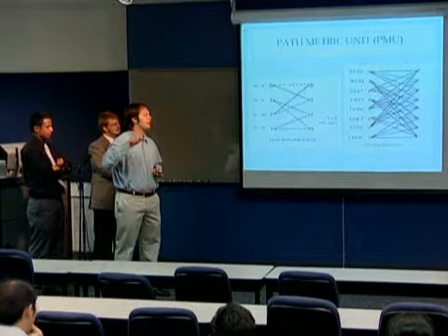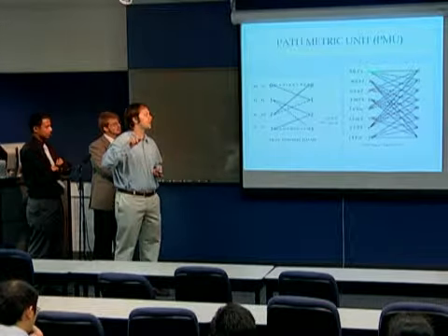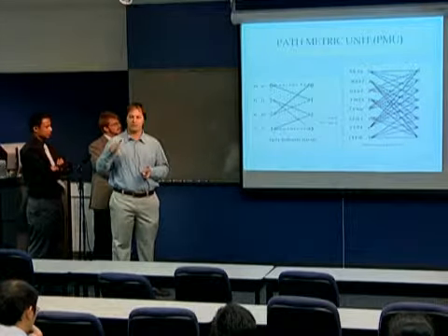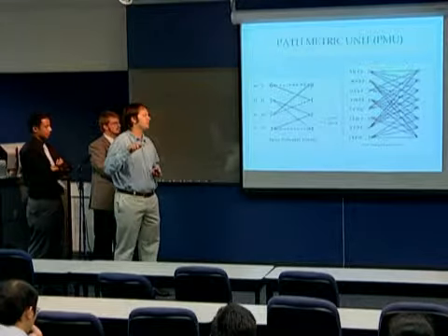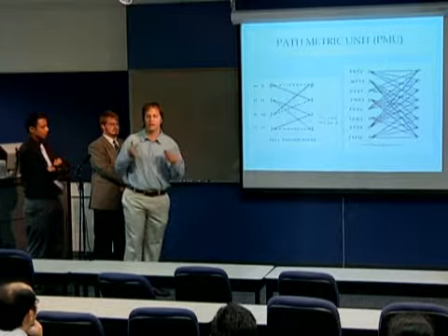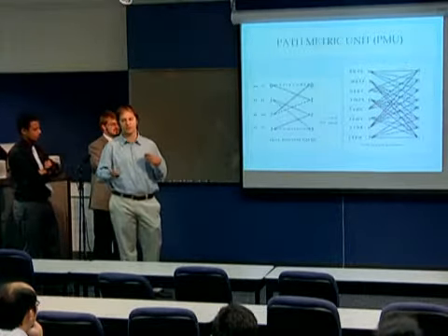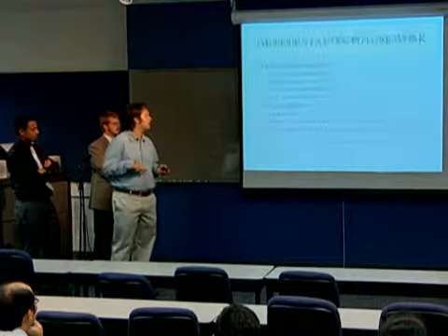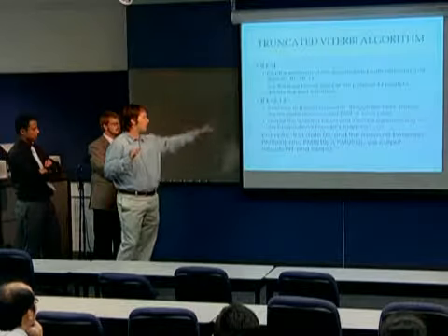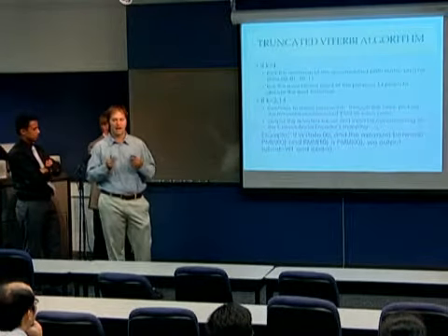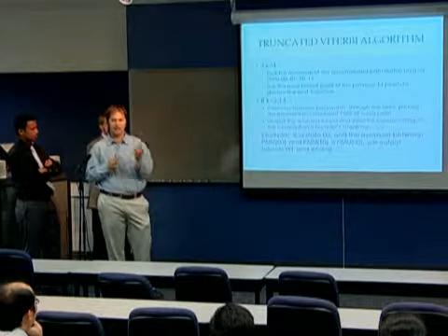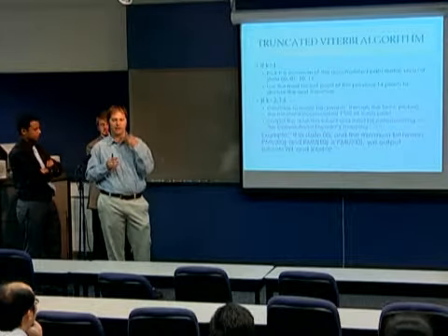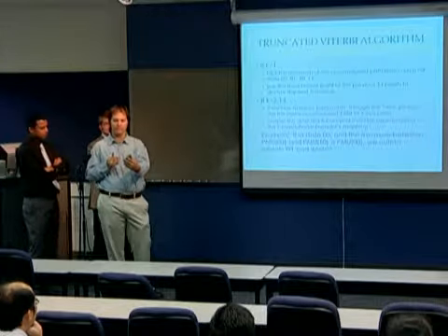Say we pick 0 to 0, this transition has an associated subset that we now know, and it also has to have an associated bit that was input to the convolutional encoder to make this transition happen. So we now know both of those things for all the points, and then we take the indices that we took from the branch metric unit.